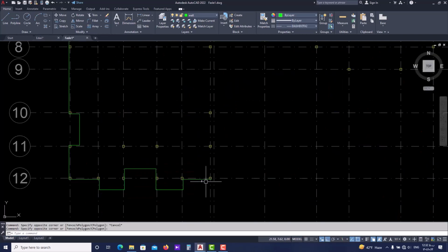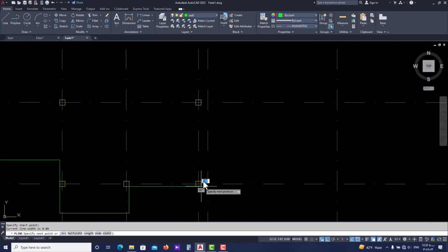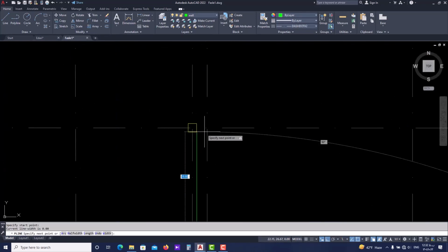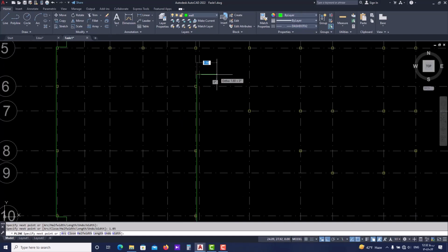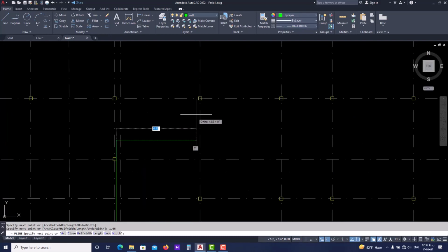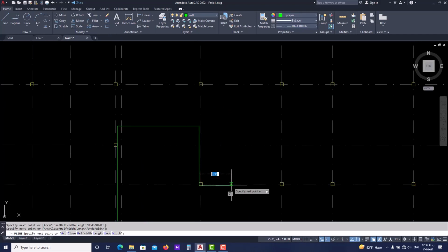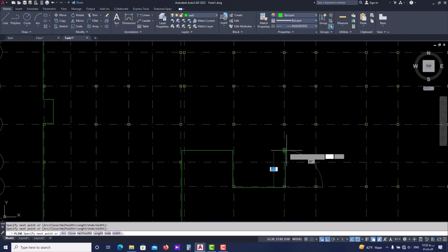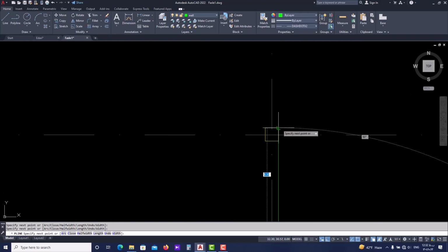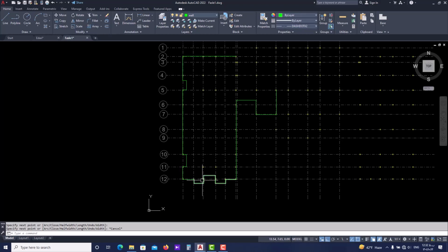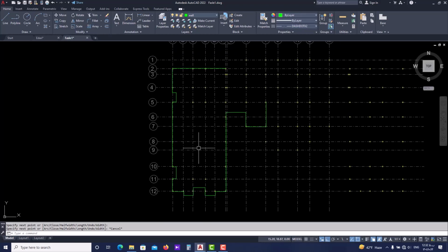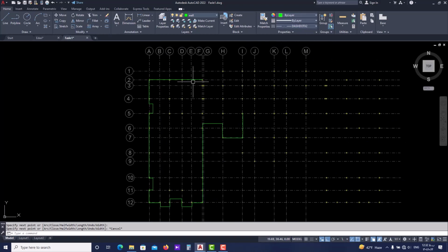this side. All right, so PL again, and we said we're going to draw this up to 6 axis, then 1.5 meters up, then we continue this to axis H, and after that to this side, and here up to axis 5. Okay, so as you did, we actually did the most of the plan with polylines, and you actually need to try to do that as well.